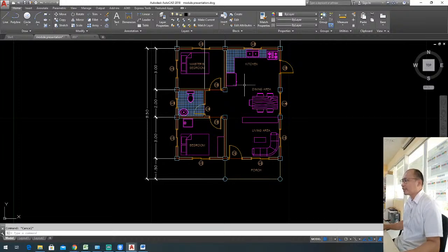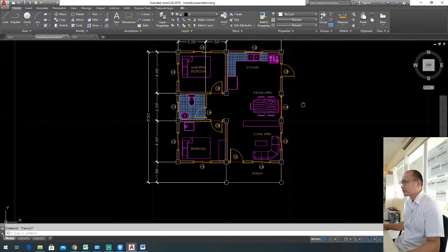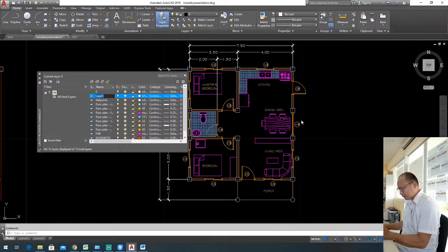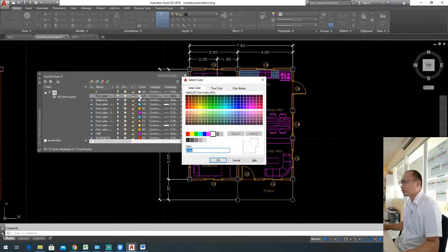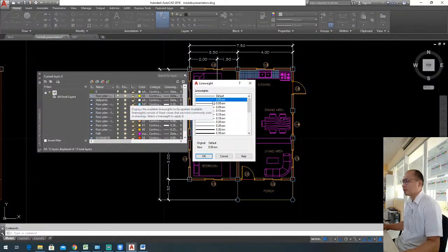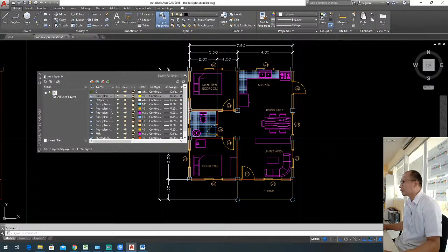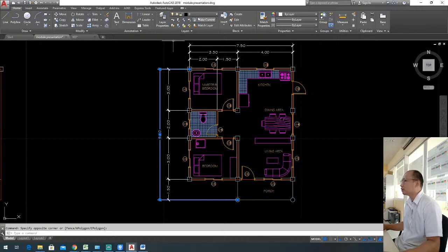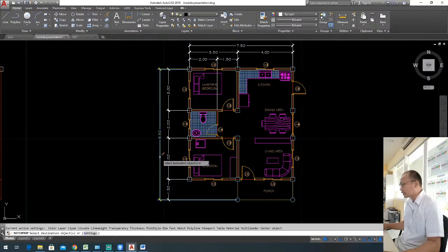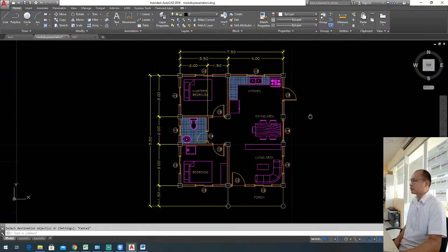Now, after providing dimensions, the next part we're going to do is, again, layer the dimensions, if and only if we haven't forgotten something to dimension. So, I'm going to go LA, and then New, and then floor plan dash dimensions. It's easy as that. Then, I'm going to go on colors, and for example, yellow. And then my line weight would be like 0.0, and then exit, and then choose 1, for example. And then schedule that one on the floor plan dimensions. And then go MA, enter, and then click, and just simply highlight the rest of the dimensions. Okay?